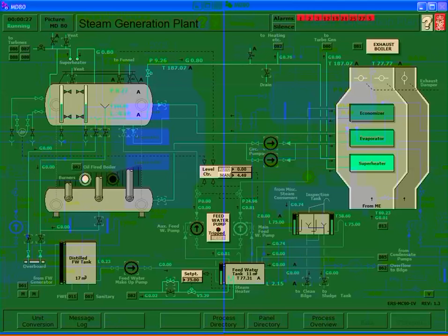When you were to run the cargo pumps, you would be putting this up to 85 or 90% of its capacity, and I would have to use this bigger pump, and you also have a bigger condensate pump. So this one is very small in comparison, designed for heating services and combined cycle, and then this is designed for running those big cargo pumps. And we have circ pumps that circulate water through the evaporators with their generating tubes right back to the drum. The feed pump goes into an economizer, and we have a superheater for running that steam turbine.